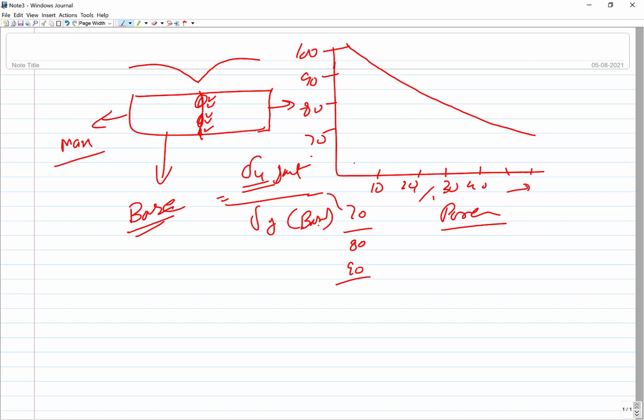So the point here is the maximum you can gain for a good joint, free from defects and no interlayers, is very close to 100% joint efficiency, maybe 96, 97, 98%. But if there are porosities and discontinuities in the diffusion bonds, then the joint efficiency will be poor. That's one aspect.